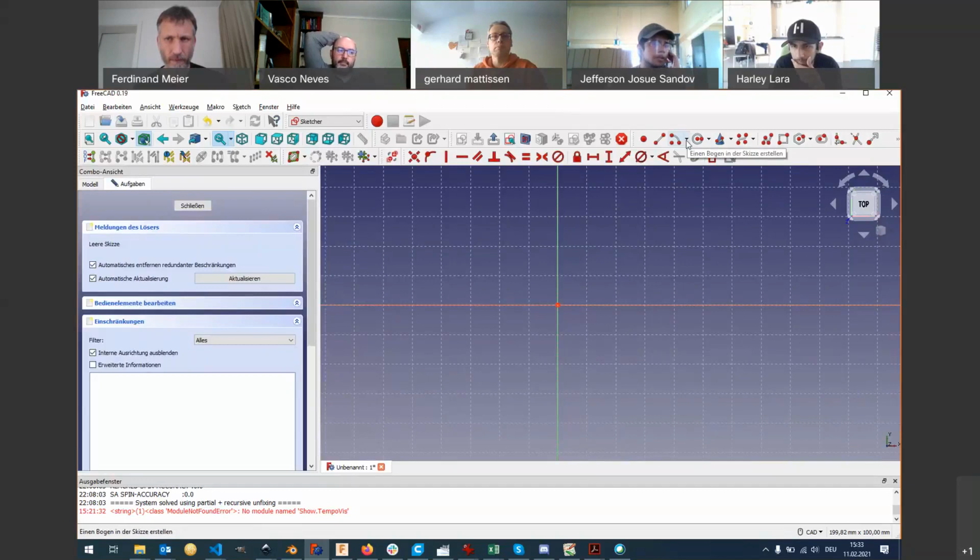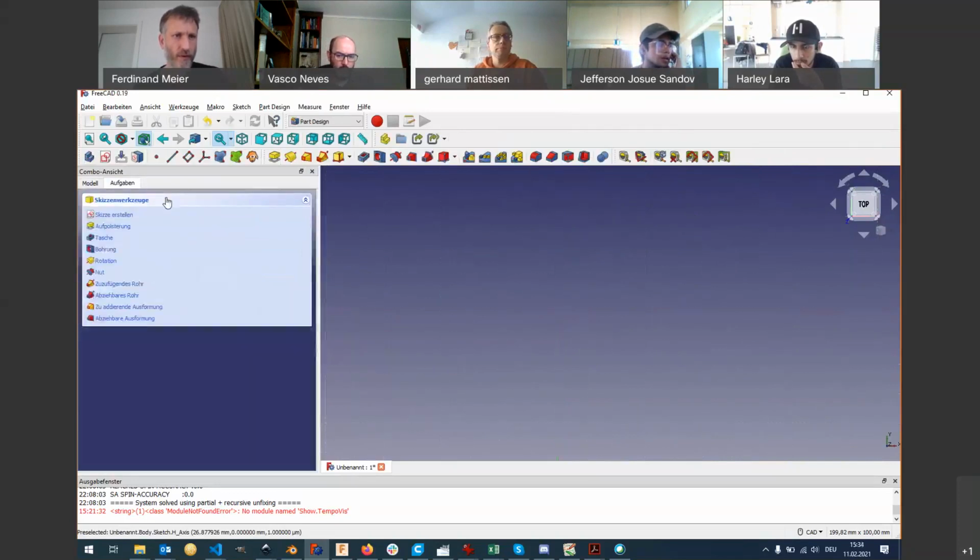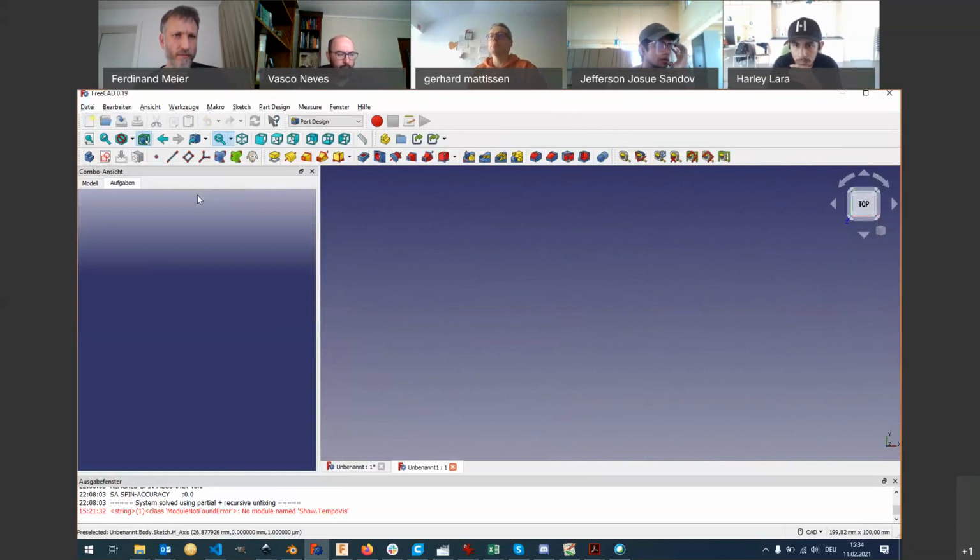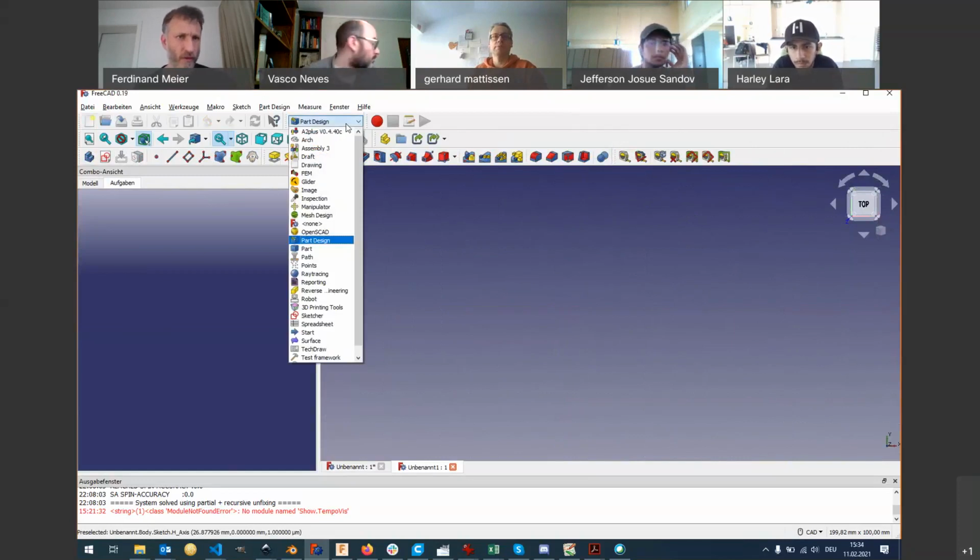Before you start, I got lost just in doing the sketch. Okay, I will quickly repeat. So I make a new file. I switch to the part design. There's a little drop down somewhere top in the middle, and I select part design.